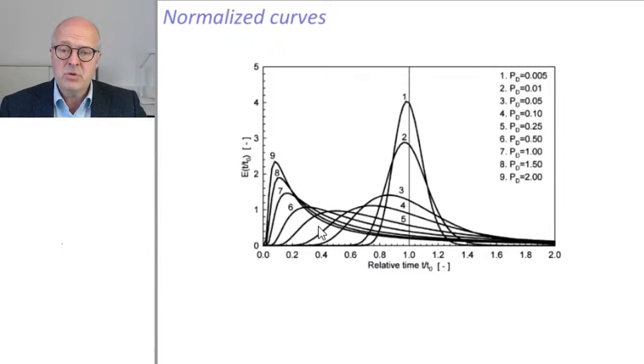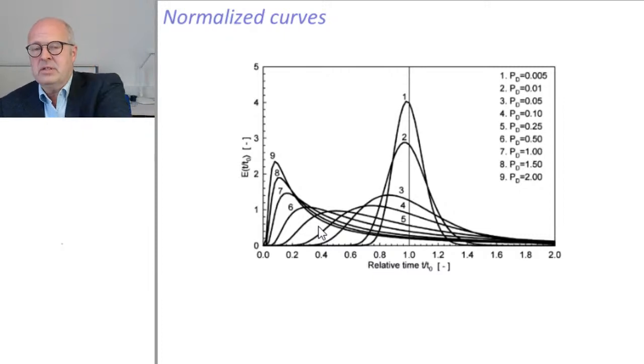So the argument was made that it could be done, that you could have a pesticide factory and evaporation ponds to actually separate water from traces or remnants of pesticides in the produce, because the chalk is so impermeable. And actually tests have been made, and the hydraulic conductivity of the chalk was found to be 10 to the minus 12 to 10 to the minus 14.